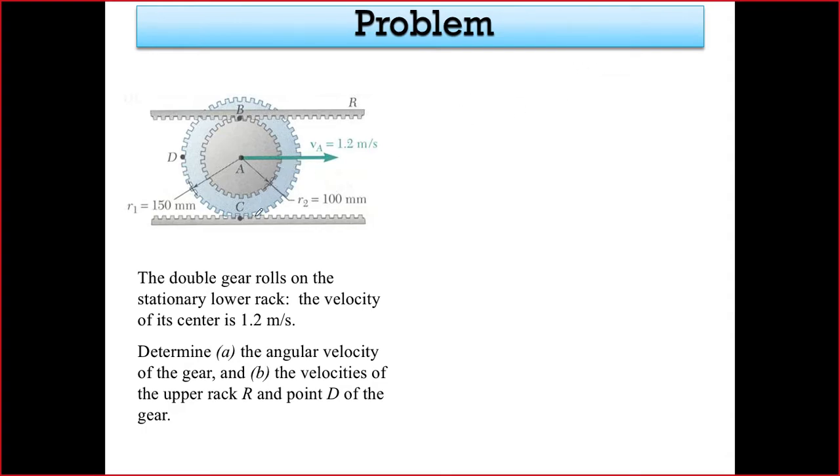मेरे इधर देखें, इधर क्या होगा, इधर अगर लेट्स से कि हमारा ये गियर फिक्स्ड हो ना, तो अब हो ये रहा है कि लेट्स से कि इधर कोई मोटर लगी हो A के ऊपर, ठीक है, और वो रोटेट कर रही है. इस केस में अगर इफ इट्स मूविंग टू द राइट, दैट मीन्स दिस व्हील, दिस गियर इज रोटेटिंग टुवर्ड्स व्हाट, एंटी क्लॉकवाइज. No, sorry, clockwise. मेरा हमेशा ये गलत हो जाता है, clockwise. So what would happen then is कि this gear moves along this fixed rack